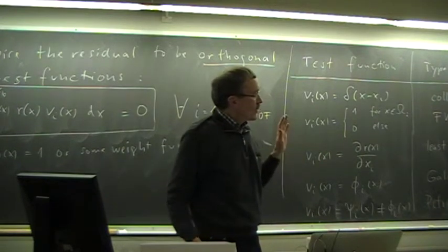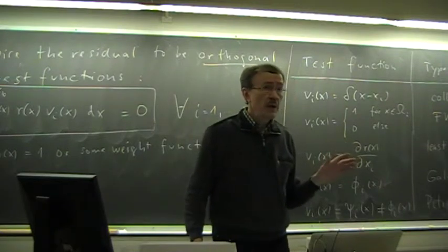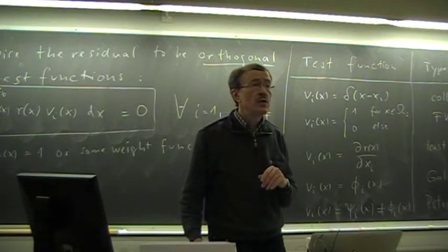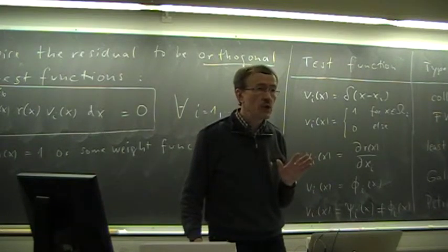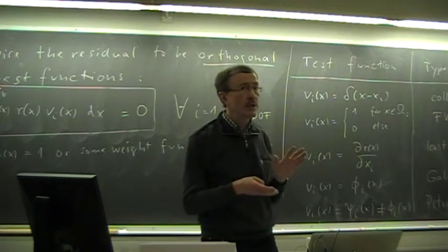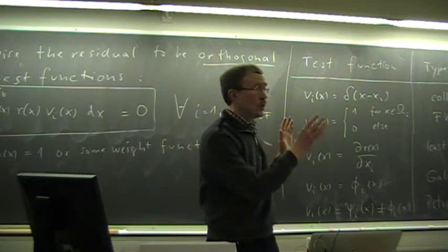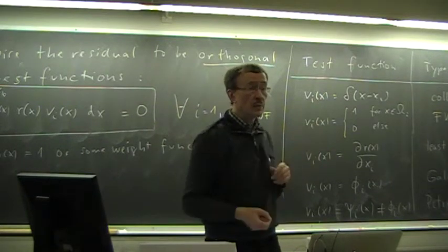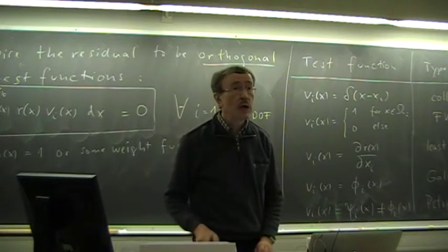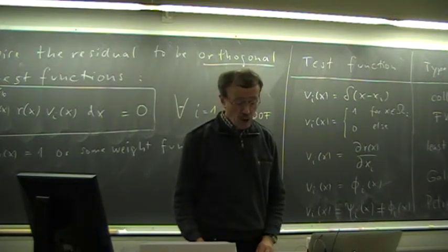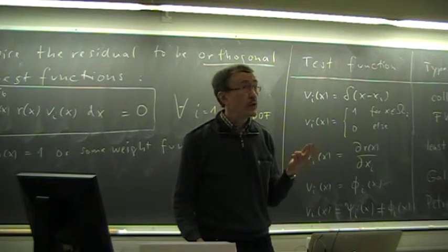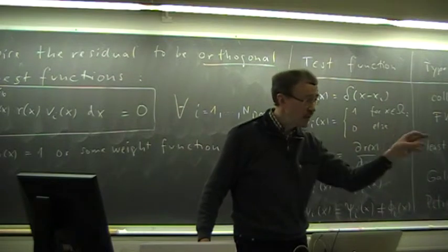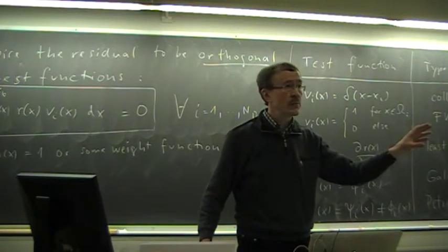Say the finite difference method is easy to implement, and has good mathematical background, but it is usually limited to relatively simple geometries in the sense that you must have a mapping from what you're doing to a rectangular domain in 2D or a brick domain in 3D. So that means you cannot do unstructured grids with that. On the other hand, the finite volume method and finite element method, you can do that. They are very flexible regarding geometry and adaptivity. If you want to get more points where things are happening, you can do that very easily.